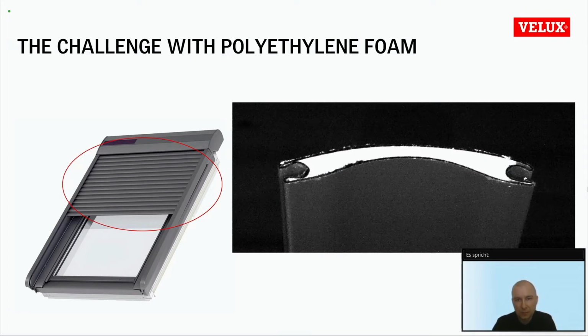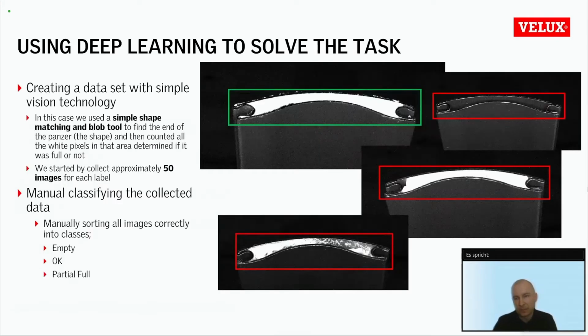But foam, I don't know anybody who is the do-it-yourself type knows that it has its own life when it comes to expanding. And the problem, as shown here, is that the foam can be filled partly, it can be badly expanded, and it can also be emptied if the nozzles are getting stuck with residues and things like that. That creates a lot of waste, and it creates a lot of attention for the operators to be aware of this to avoid unfilled profiles in the products.